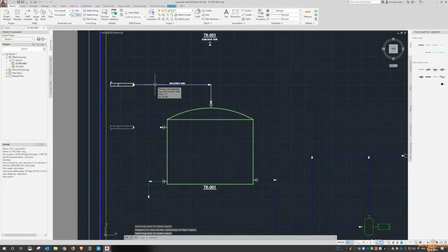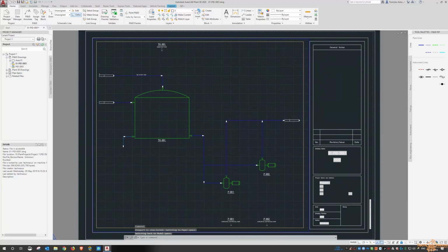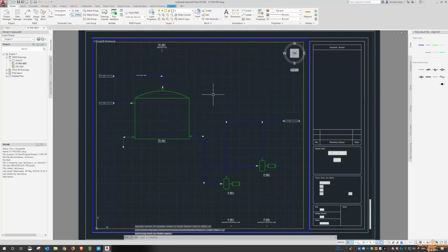So once you've done one, you can go through and do the next one, the drains, and then the others. Every project, like I said before, it'll be different. You might have a certain numbering system for primary lines, a certain numbering system for secondary lines maybe, or you just might do 1000, 2000, 3000, or 1000, 1001, and 1002 as you progress. And obviously as P&IDs update and change, the line numbering may change as well. So that's the first P&ID.